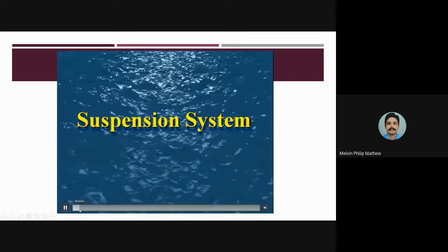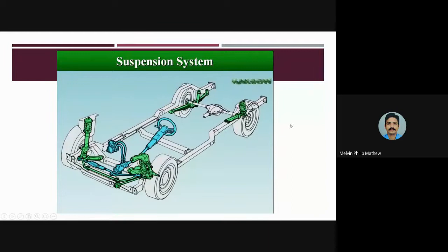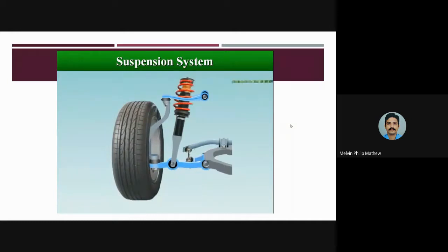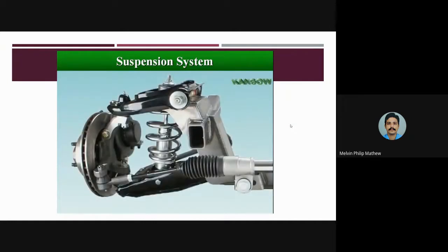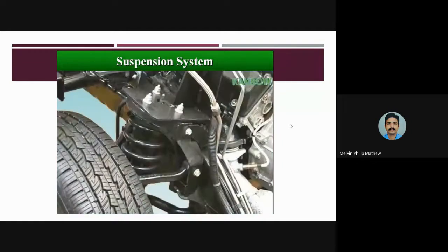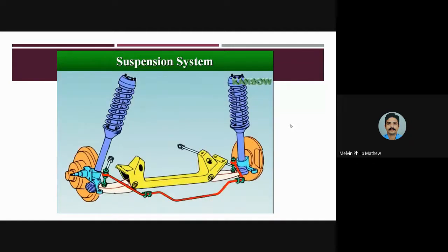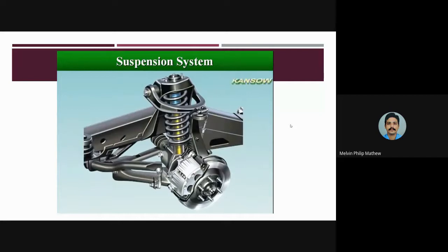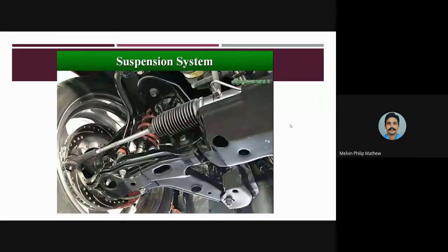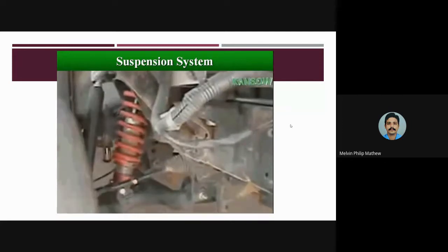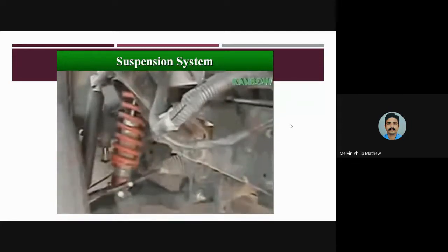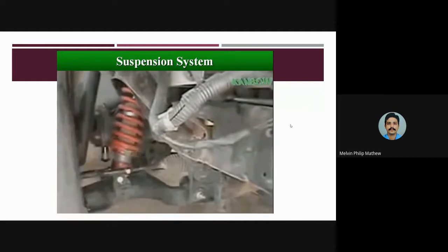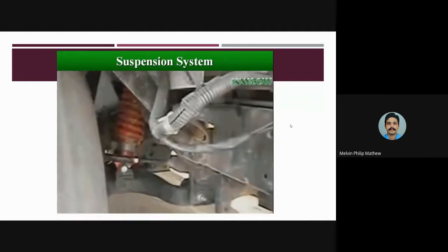Axle assembly from the suspension system is the term given to the system of springs, shock absorbers, and linkages that connects a vehicle to its wheels, and allows relative motion between the two. The suspension system separates the wheel axle assembly from the body. A vehicle needs a suspension system to cushion and damp out road shocks, so providing comfort to the passengers and preventing damage to the load and vehicle components. The springs and other components compress and expand as the wheel hits bumps or holes in the road. This allows the wheel to move up and down without moving the vehicle body.